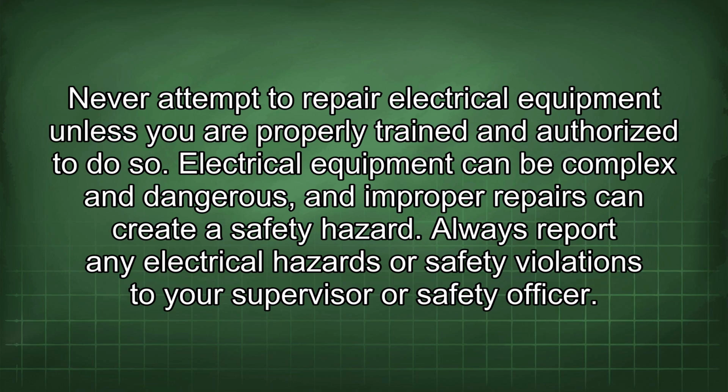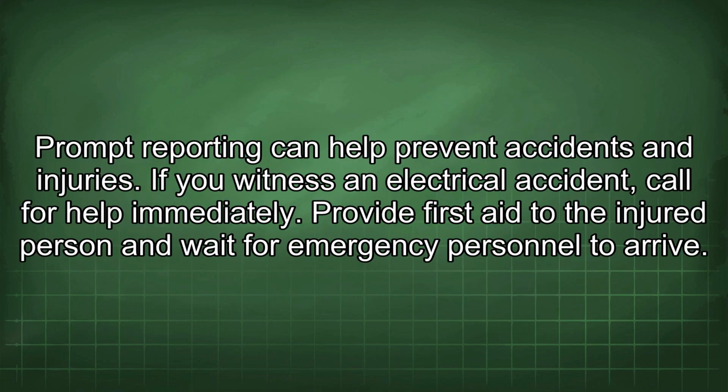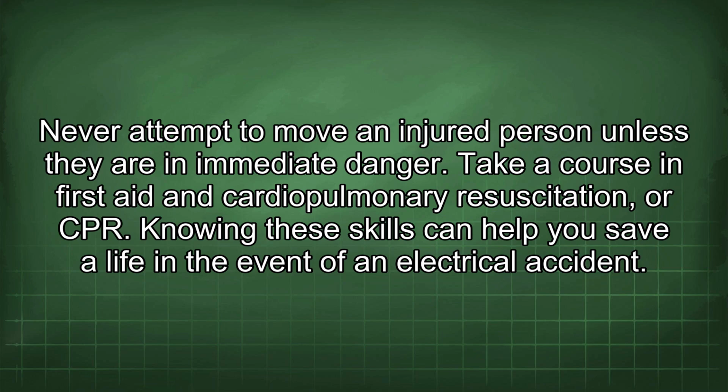Always report any electrical hazards or safety violations to your supervisor or safety officer. Prompt reporting can help prevent accidents and injuries. If you witness an electrical accident, call for help immediately. Provide first aid to the injured person and wait for emergency personnel to arrive. Never attempt to move an injured person unless they are in immediate danger.